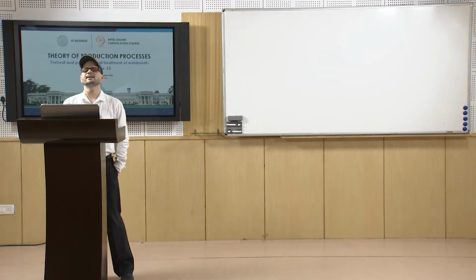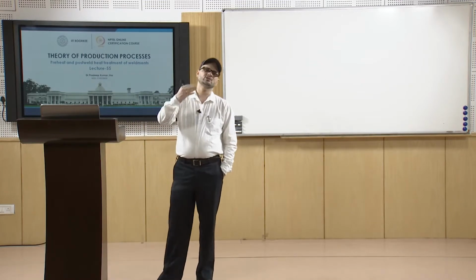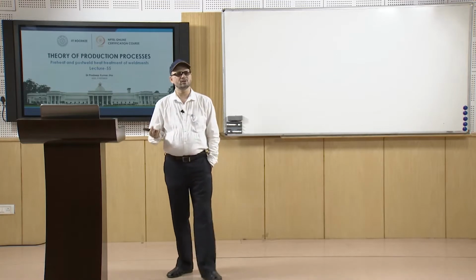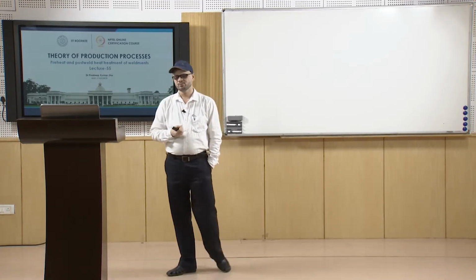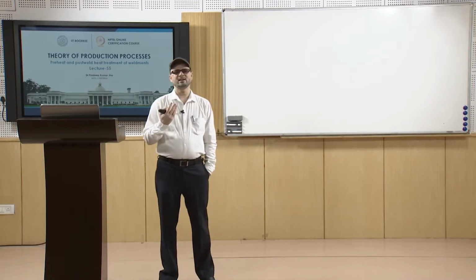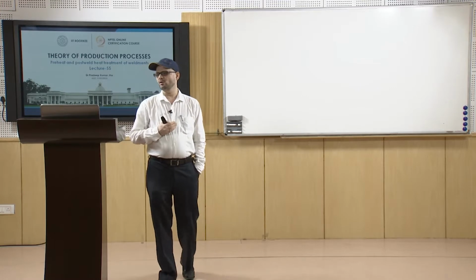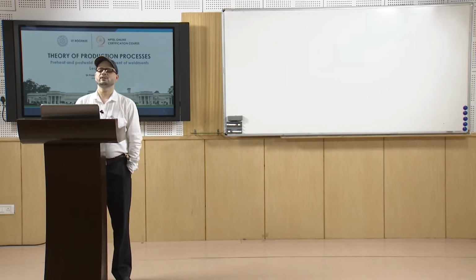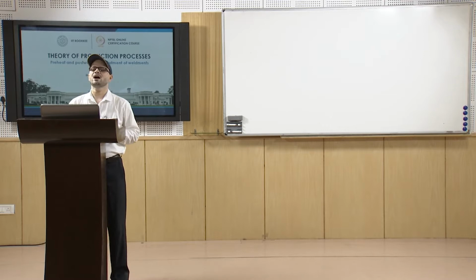In those cases the alloying elements also contribute to the hardenability, so hardenability is not only because of carbon. In plain carbon steel the main alloying element is carbon, but otherwise, for low alloy steels, we have to find the value of the carbon equivalent.